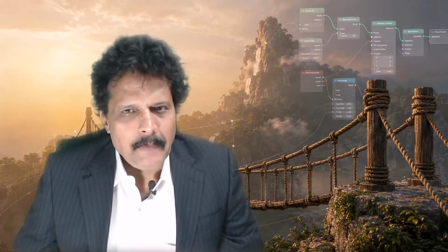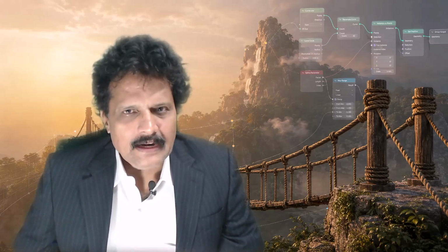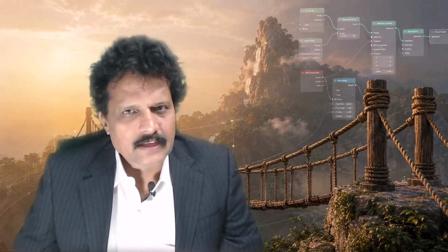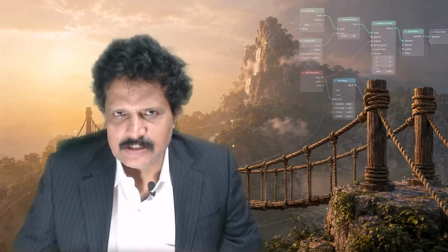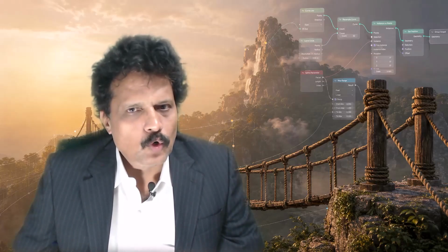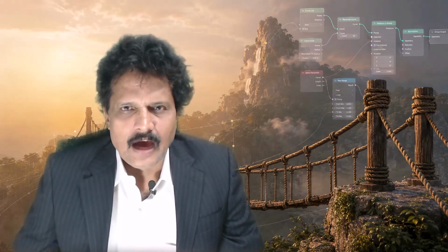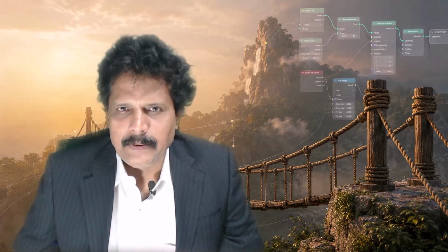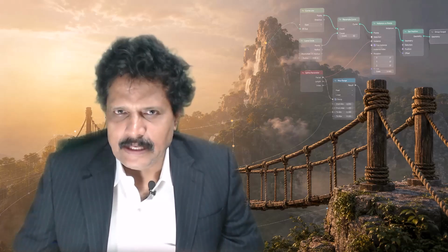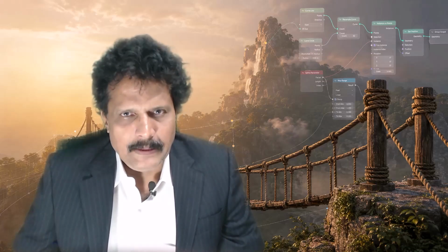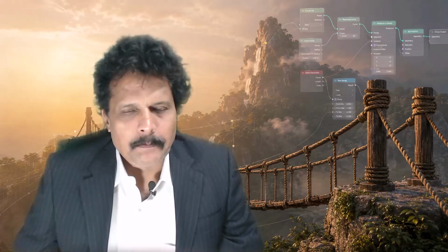We will also use spline parameter and map range to shape the pillars so that they become wider at the base and narrower at the top. Finally, we will add smoothing using subdivision surface and organize the pillar setup into a clean node group. By the end of this session, our bridge will no longer be just 4 guide curves. It will have visible rope thickness and 4 dynamic support pillars that respond to the bridge controls.